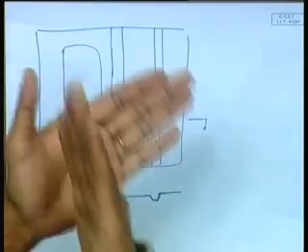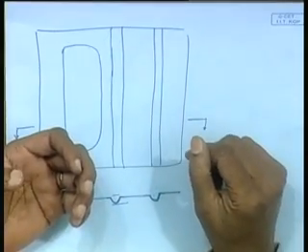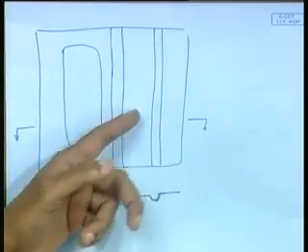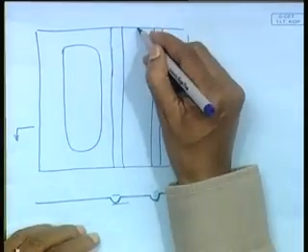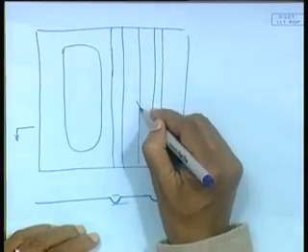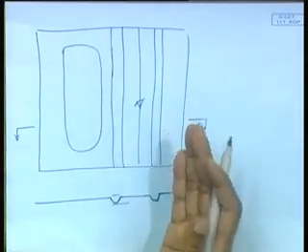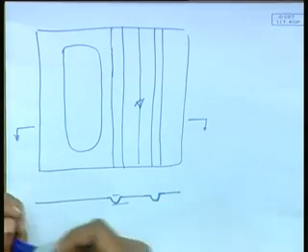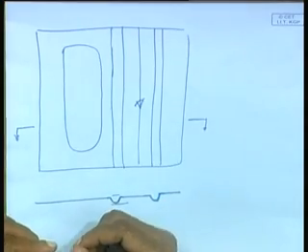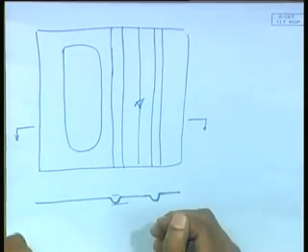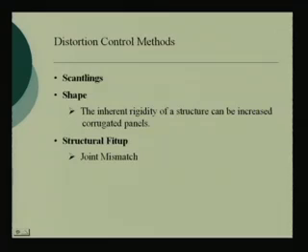How? Through a punch, through a hydraulic press. So, what welding will come here? Probably some butt weldings only. Some pieces of plates are to be welded, and the strength is being provided through corrugations. So the shape is one way you can control distortion, because you are avoiding welding, minimizing welding.